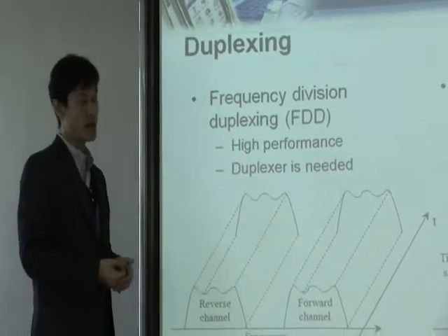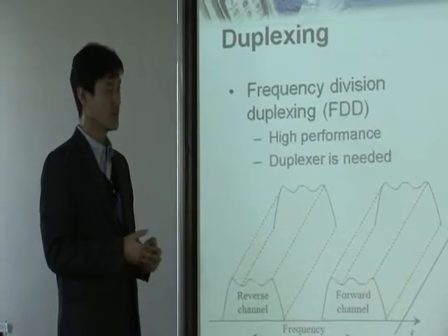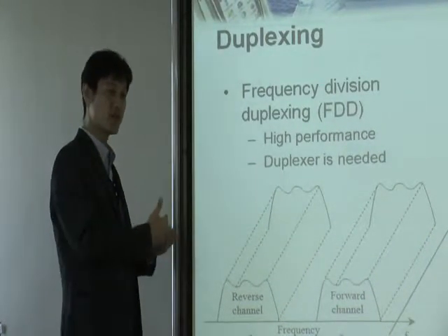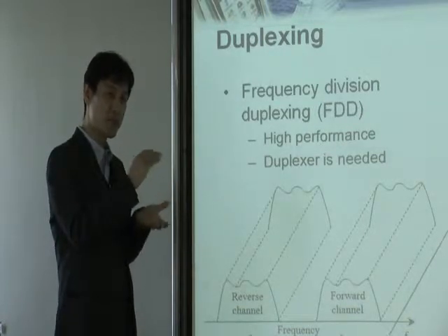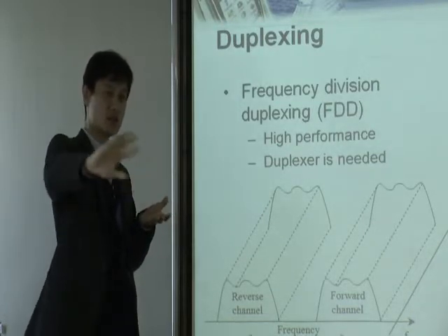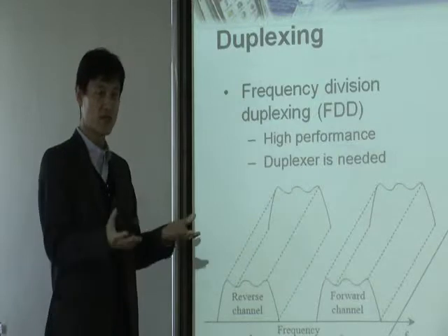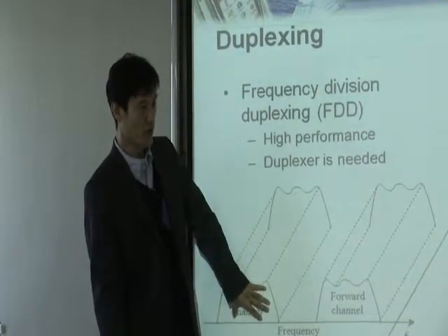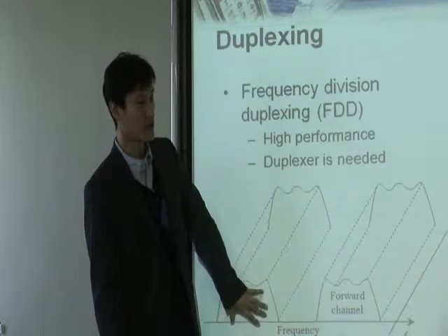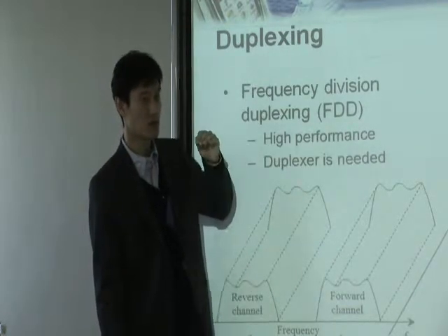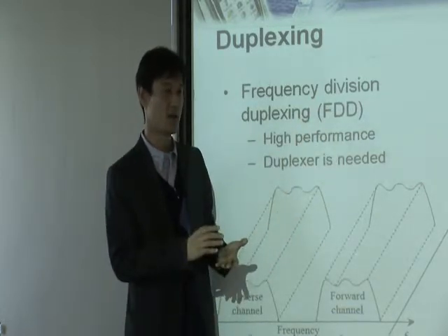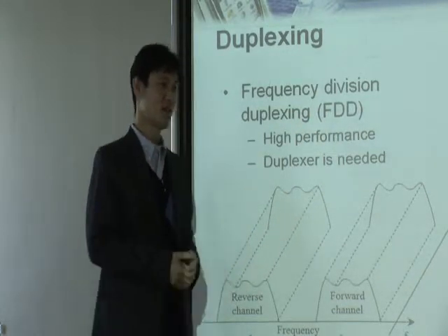In that case, by physics, you have more attenuation. When you have a low frequency, typically even with the same power, it propagates a longer distance. That's physics. So therefore, in uplink, you want to have a low frequency so that you can make the transmission go a little bit longer with the same power. Why is that? Why is that?